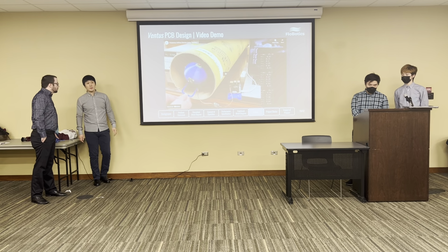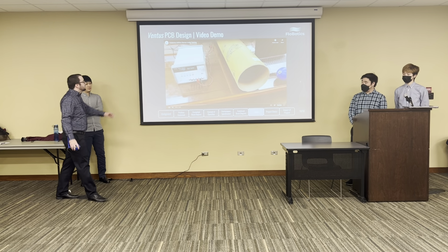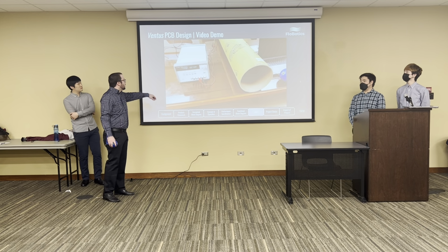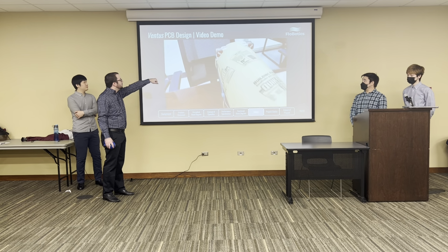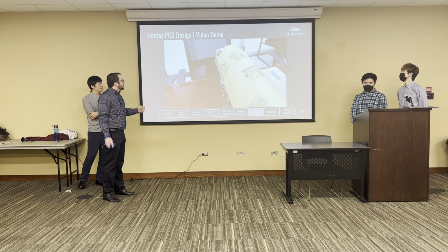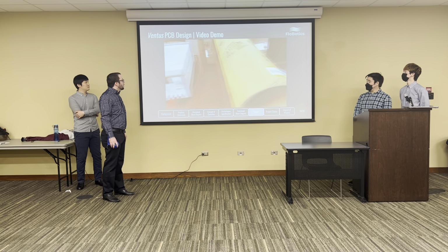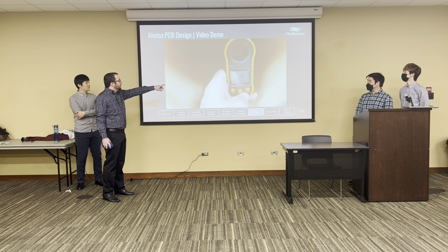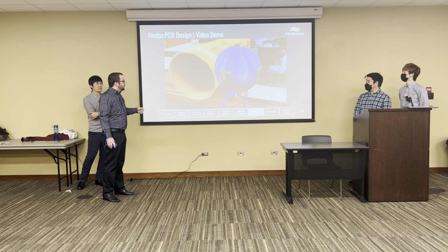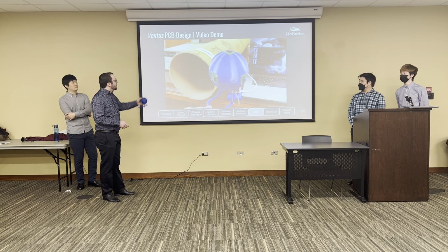Here's our video demo. All right, you can see we have a variable power supply, which we have connections running to the back where our 200 millimeter fan is. We're varying the voltage. And then here you can see our airflow anemometer giving us a readout. So when we adjust the voltage on the fan, we'll be able to set that value to what we need it to be. And then here's a close-up of the sensor array.